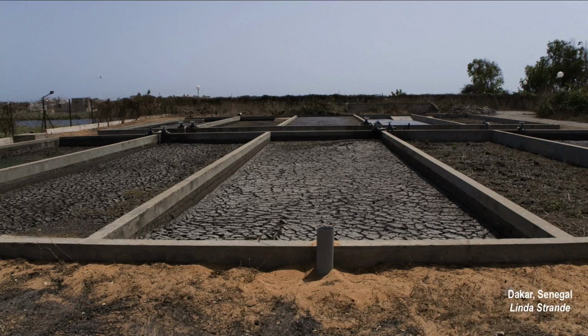Here's a great example of a sludge drying bed. The sludge trucks from the previous slide would come here and dump their sludge onto one of these dedicated drying beds. The beds are made from layers of gravel and sand. The sludge is applied on top, and the solids stay on the sand layer and dry out under the sun while the effluent percolates through the sand and down through the gravel where it's collected. The effluent, don't forget, is another new product that must be treated in a separate process before it can be discharged into the environment.